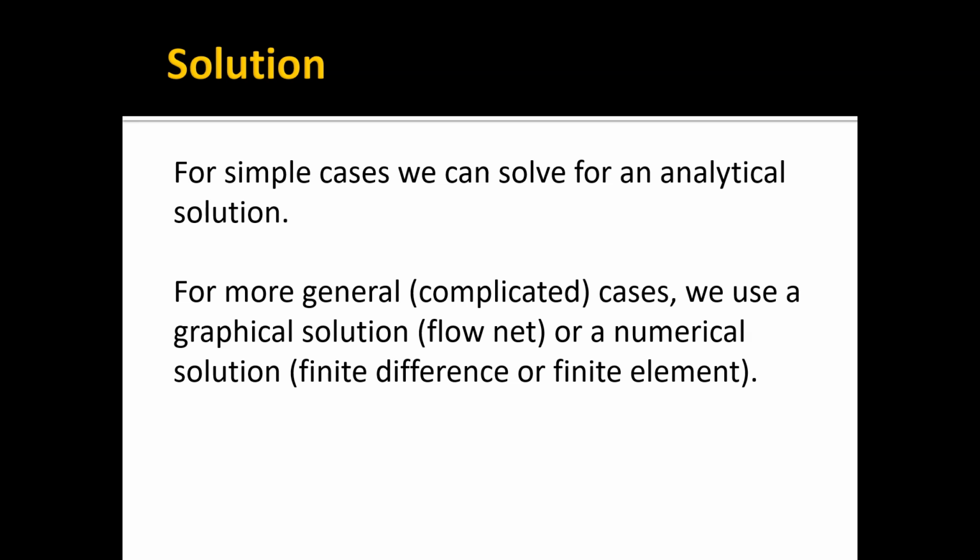Typically a finite difference or finite volume solution or finite element. And again, I just illustrated for you a numerical grid. For each of these numerical solutions, typically you subdivide or discretize the aquifer geometry into a series of small cells or elements, and then you look at each cell and compare it to its neighboring cells, and you make sure there's a way to force the governing equation to be satisfied at that small scale.